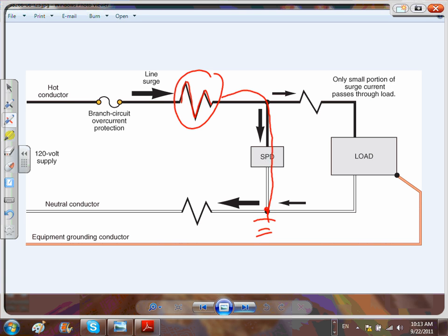By the way, do you know that, guys? If you keep increasing the voltage, it can jump the gap of air. You see them in a transmission line. The closer you get to a transmission line, within a couple of inches, an arc will jump from the transmission line to you and electrocute you. If you get a grounded object closer to a transmission line, within inches, depending on the voltage, it will ionize the air and turn the air into a conductive object and conduct the current in an arc directly to the grounded object and to Mother Earth.